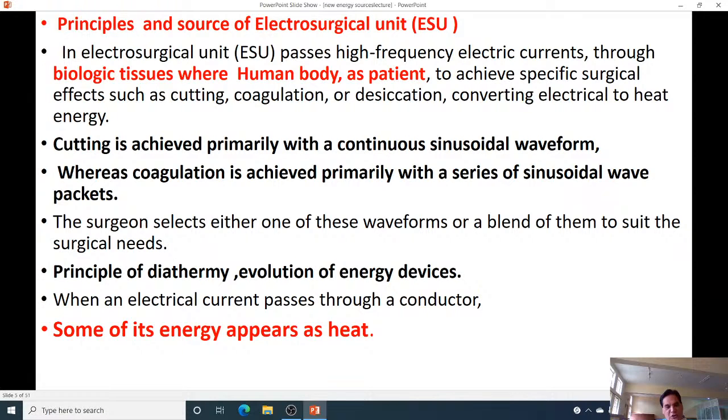Understand? If an electric current passes through our body, we will get convulsions. With high frequency, the patient may die. But we are using it under specified conditions, and our aim is to achieve specific surgical effects such as cutting, coagulation and desiccation. How do you do it? By converting the electrical energy into heat energy. This is the principle. There are two types. Cutting is achieved primarily with a continuous sinusoidal waveform. Energy is in two forms: a continuous sinusoidal waveform for cutting. Cutting is primarily done by monopolar, whereas coagulation...